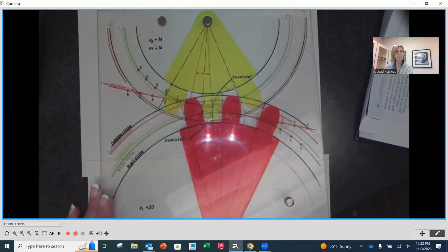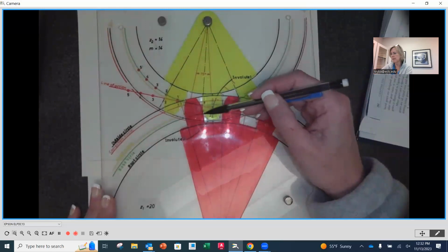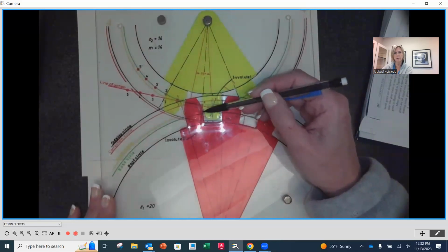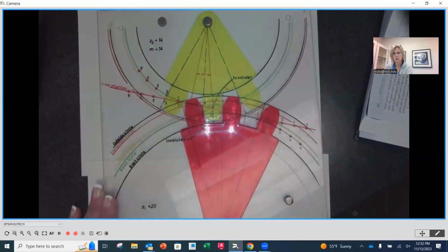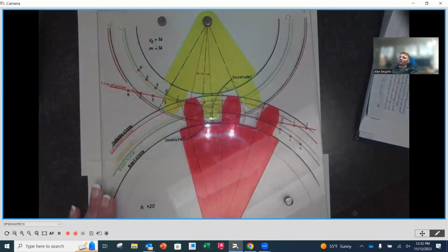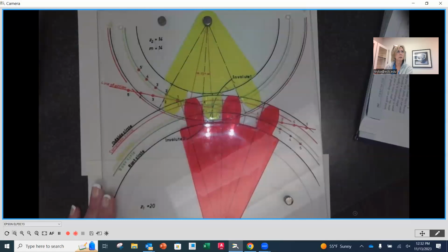Well, yeah, okay, but why would they heat up and crash? Why is it important that the dedendum is larger than the addendum? Wouldn't they just bind? It's going to be quieter. We don't want to have interference, right? We don't want to have metal shavings right off the bat, right?